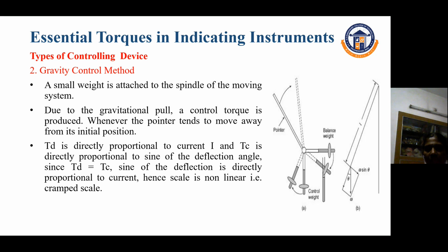So this is a gravity control. It will be perpendicularly used. Once the pointer moves from the starting position to the end position, this gravity will help the pointer to deflect and also come back to the original position.